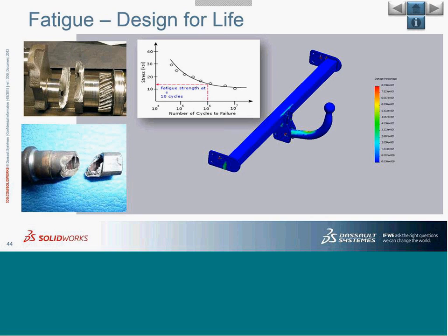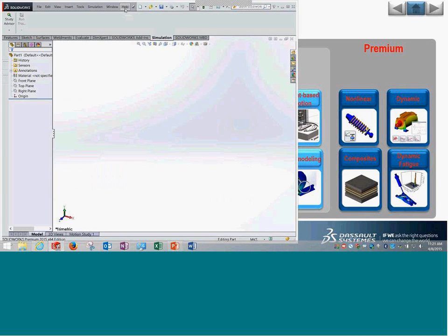What else? It is basically comparing the stress variations or the mean stresses with a particular diagram called the SN curve, which is the amplitude stress versus the number of cycles that a component might fail at that particular amplitude of stress, and that is used for understanding the life of a component. So the working is very simple. Example again from the tutorials.